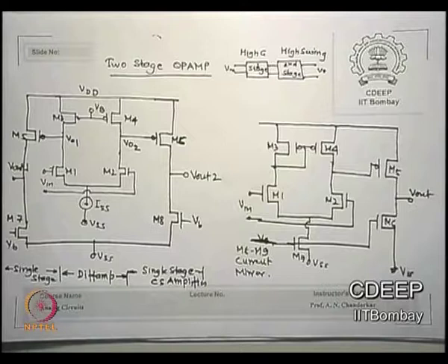So a typical OPAMP may have a gain of how much? 10 to the power 4 to 10 to the power 5. A typical OPAMP will have gain outputs of the order of 10 to the power 4 or 10 to the power 5, okay, or maybe in the best design even higher, but it may have some other problems if we get too much gain. Okay. So is that point clear? OPAMPs are no different from amplifiers which we have already designed and seen how they are solved.